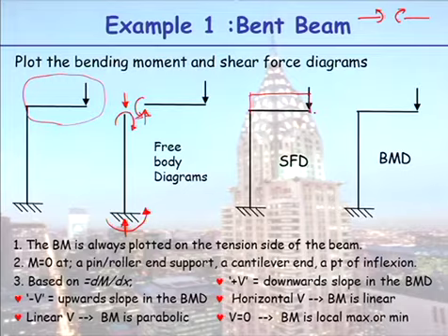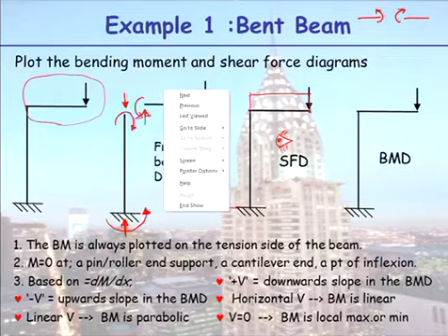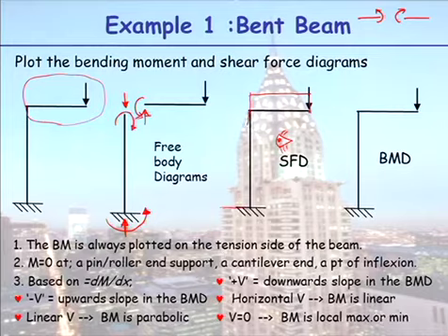Now when I draw shear force, up till now I've said shear force is vertical force. But to be more exact, shear force is the force perpendicular to the beam you're considering. So now when we look at this vertical face, shear force would be the horizontal forces. You have to define what side you're looking at it from, so we draw a little eye. If you look at it sideways, there's no force in this direction. There was no reaction, so therefore I have no shear force in that part of the beam.